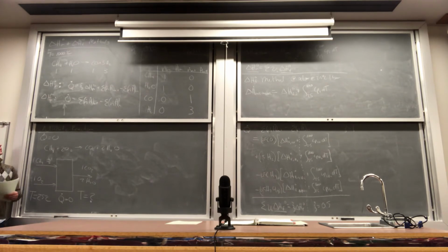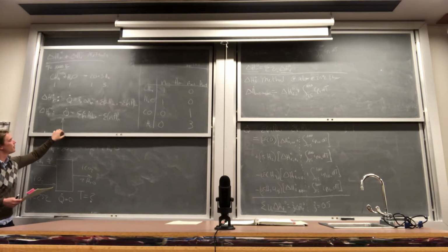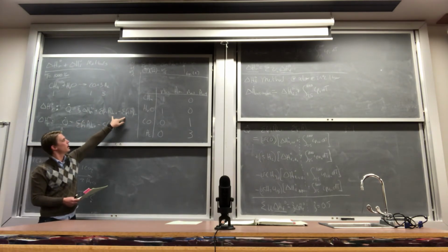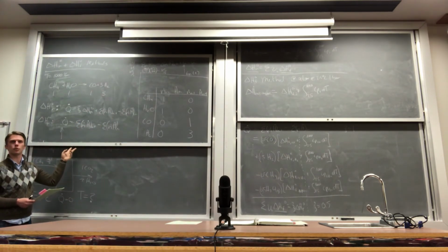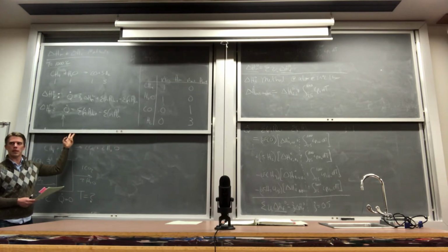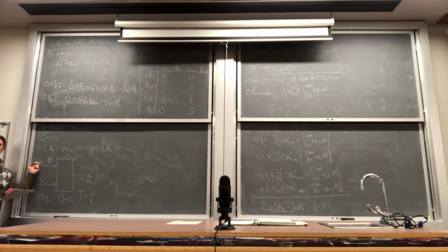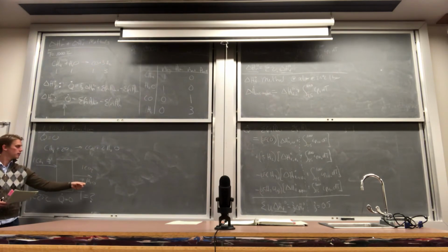In the adiabatic reactor, we are effectively saying that all of the energy that is either consumed or released by the chemical reaction has to be distributed into the individual species in the system. So in this circumstance, we are breaking the CH bonds, breaking the OO bonds, and forming CO bonds and HO bonds.